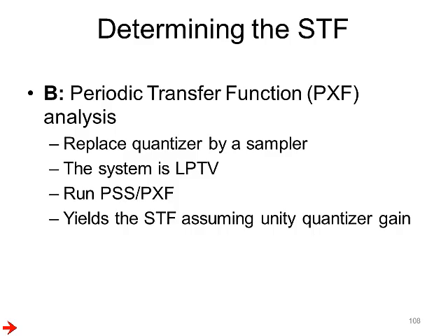To perform this analysis, however, one needs to make sure that the system you're simulating is actually a periodically time varying one. Unfortunately, a delta sigma modulator has no periodic steady state in the sense that because of the presence of the quantizer, it's virtually impossible to get the simulator to converge in the PSS analysis. This can be fixed by removing the quantization noise source.